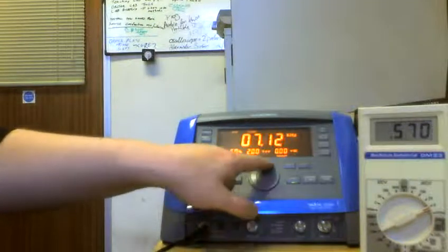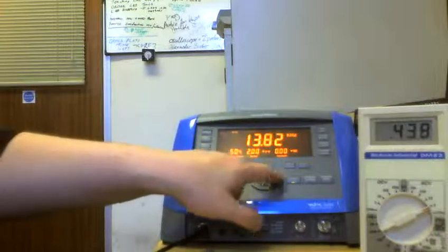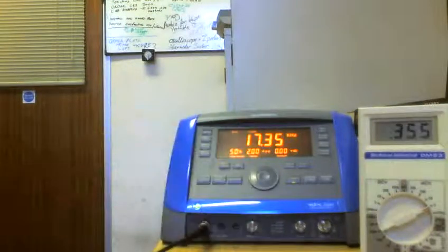At 5, we're down 100 millivolts, and up we go all the way up. So you could say 2 kilohertz is about a maximum, so from 10 hertz to 2 kilohertz your multimeter's fine. Above or below that, it's pants.